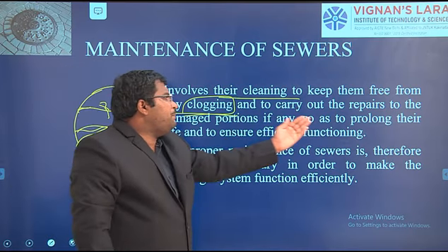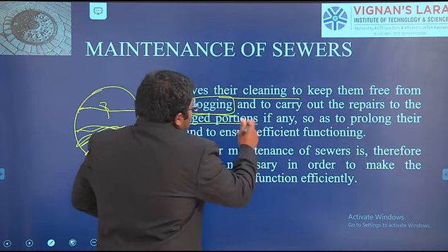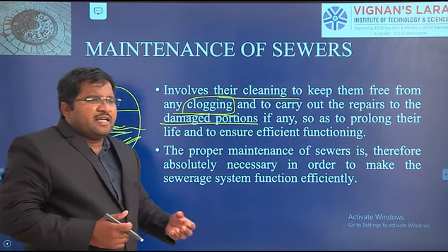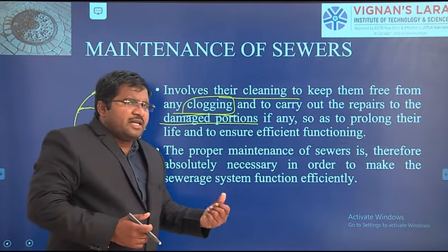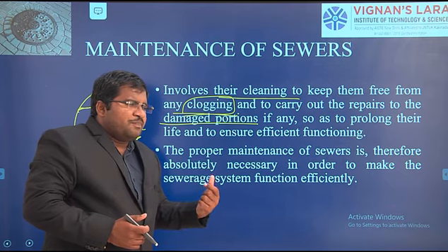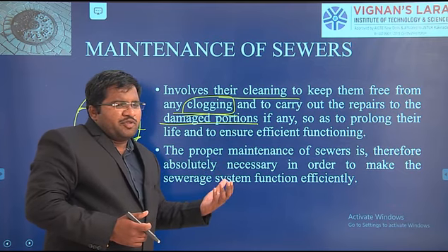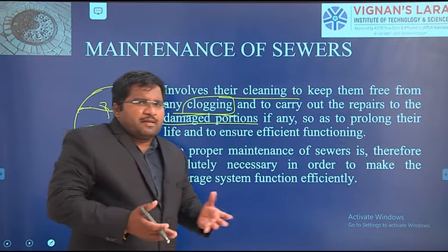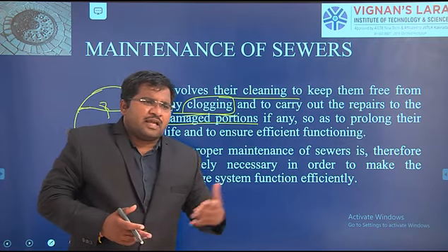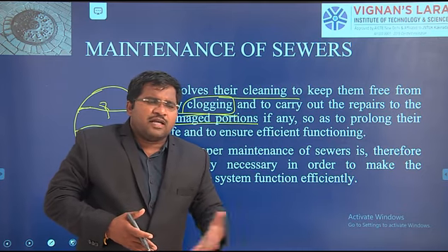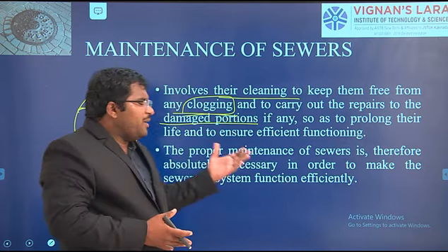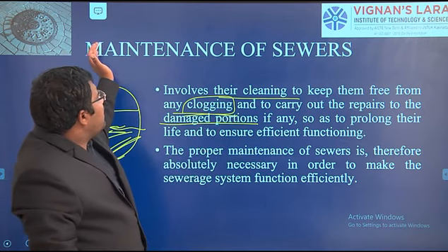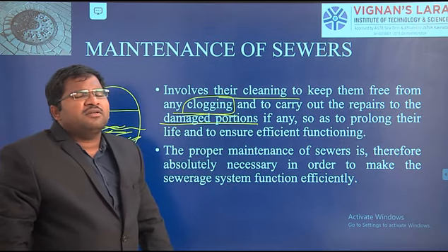And carry out the repairs to the damaged portions. This is one part. And next, whenever you use vitrified clay or asbestos cement pipes, and you apply some load on the top of the road, they are unable to withstand the load and they are going to break. Otherwise, if there is any construction activity or road activity, the pipes will get damaged. So we have to repair the damaged pipes under the section head of maintenance.